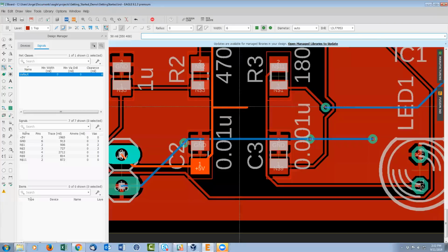For a 1 or 2-layer board, that works pretty well. It's pretty easy, even for more layers. The other option is a spacebar. That's the option I usually use. I tend to like the spacebar myself also. Yeah, I like to use the spacebar. Okay. Once you left click to place the via, you'll notice that the routing continues on the other layer, and that becomes the active layer. You'll see it up here.